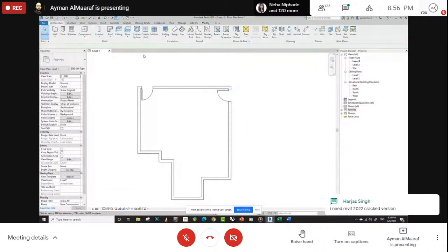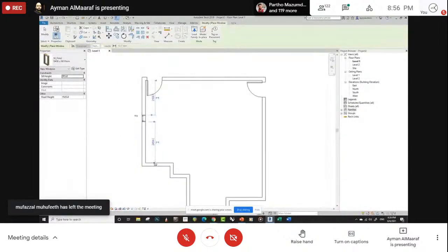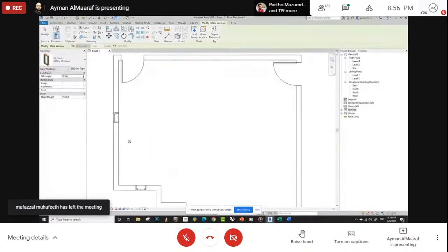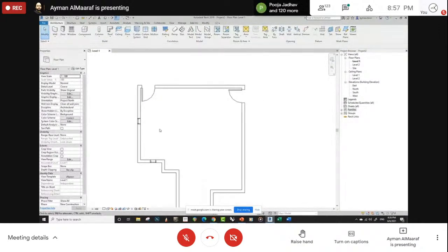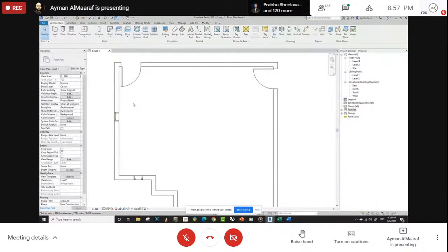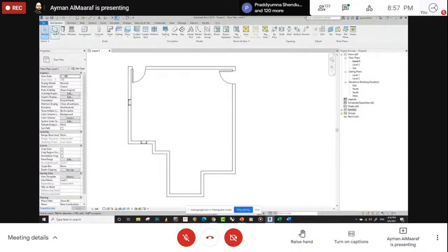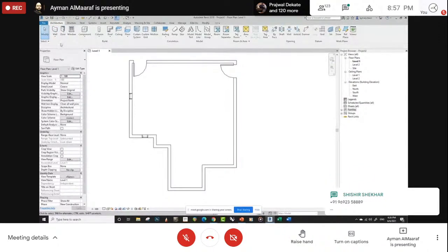This will be just not right. You will also create windows. You can create them in the walls themselves. You can't draw a window outside the walls. So this is one of the first mistakes you'll get. Maybe if you don't know how Revit works, you just click door and you can't do anything. So it's a little bit frustrating. So the things that we learned until now, that we have walls, we have doors and windows. Walls are geometry that we can draw in the model, and doors and windows are stuff that are hosted on it.